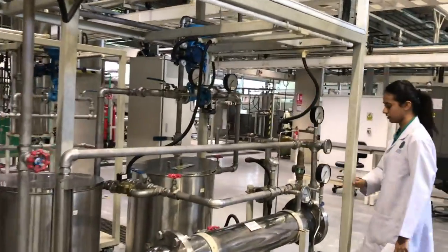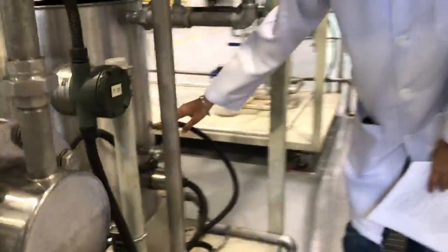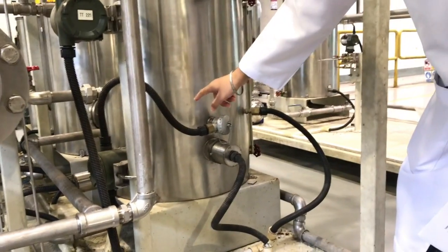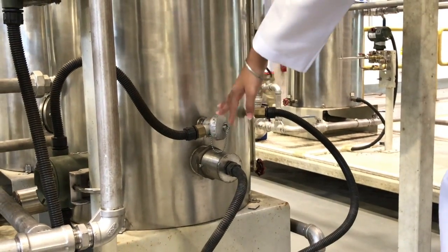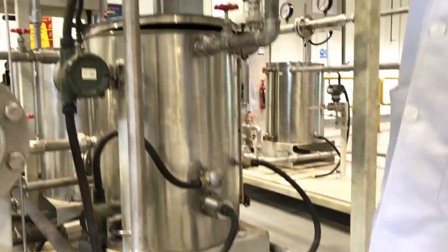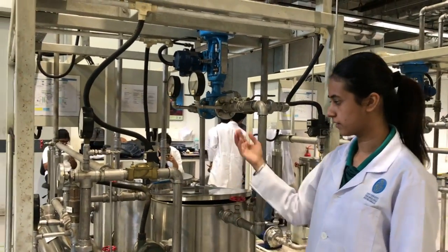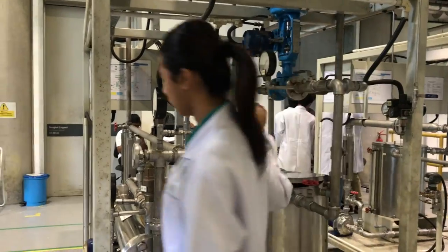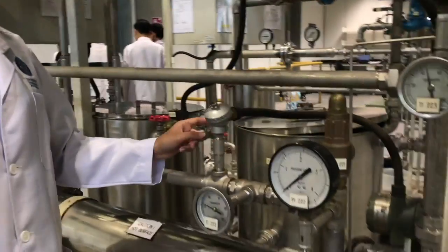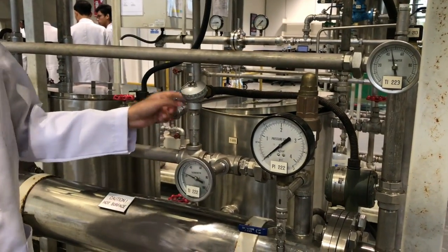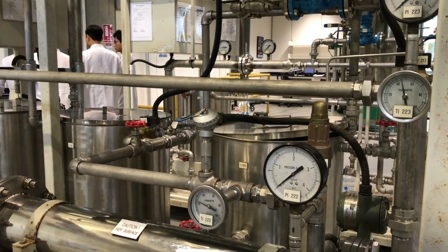And at the first side, there is a thermocouple and a transmitter that will send the readings of the temperature controller to the control system, and through that we can manipulate the temperature of the hot water and know what the temperature is. And the same goes for the product: once the cold water comes out from the shell and tube heat exchanger, we can know the temperature of the product from this transmitter over here, which will be sent to the control panel for us to determine later on.